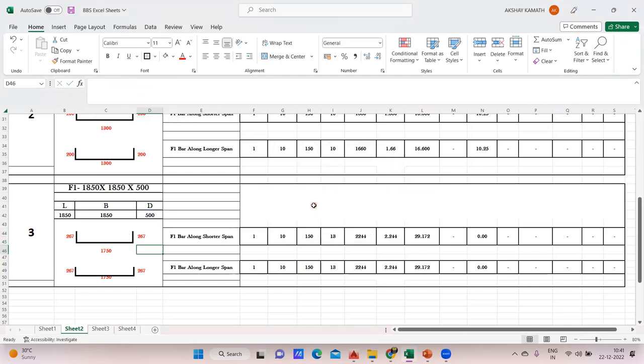Okay, now it's correct. See, it's coming to 67. Earlier it was coming to 66 point something. So now it is 267. Okay, fine. Getting my point? What I did? I did round up here. So when you do round up and put a comma and say 0, it will take the next higher value. Got it? Because practically 266.67 is not possible on the site. Okay, fine. So that's it.